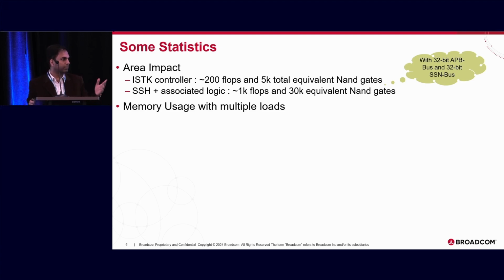Okay, so I think I'll be coming to your question on that memory usage, right? Because we are talking about deterministic patterns here, as opposed to, let's say, logic BIST or something, which is a BIST, and you just trigger it. Here we are talking about deterministic patterns, and the data volume is huge, right? And we are trying to utilize the on-chip SRAM.